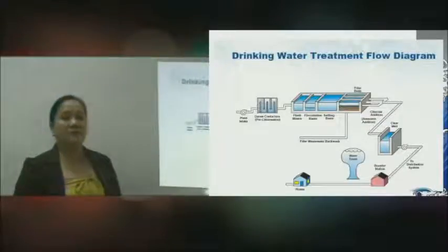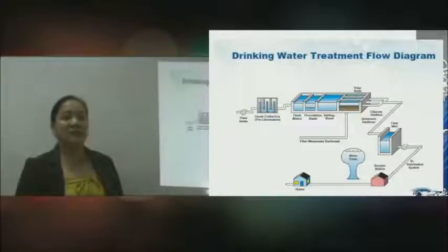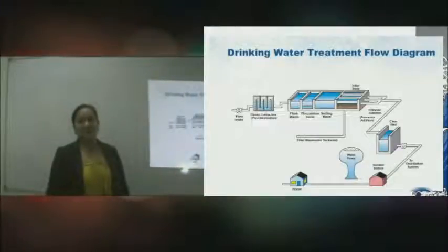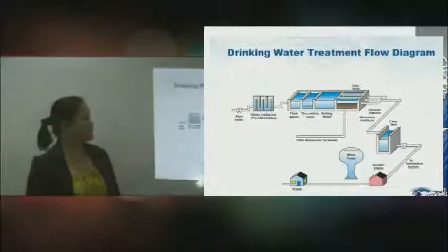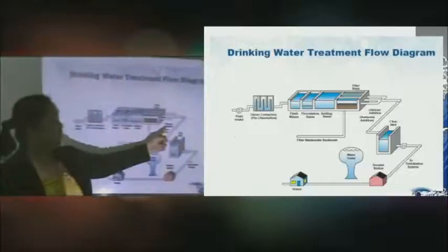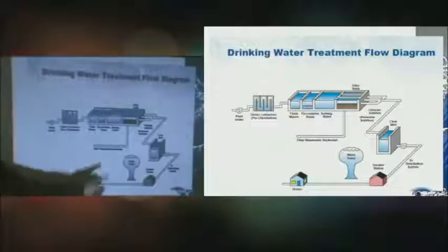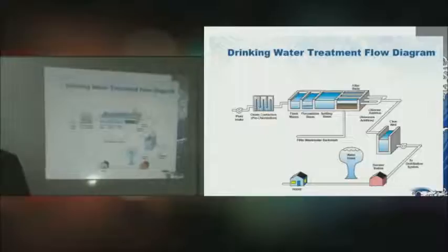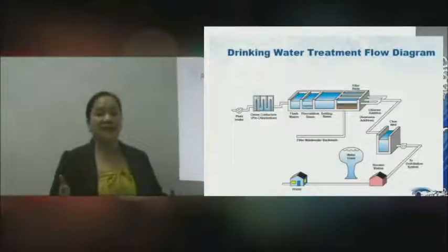However, that would also pose some risk. For example, a certain chlorination tank of Maynilad somewhere in Noveleta exploded because of the usage of gas. So they shifted back to liquid chlorine. Now, since chlorine is a gas, it easily dissipates. Therefore, you need a well. This well would normally give a longer contact time between the water and the chlorine.